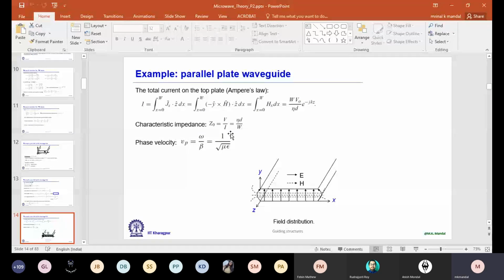When we buy substrate materials from the market, the thickness t is actually predefined. You can't tune it, so only some standard values are possible. So let's say you bought the material, then you know your epsilon r and the thickness is defined. So you choose your w value to obtain the characteristic impedance.